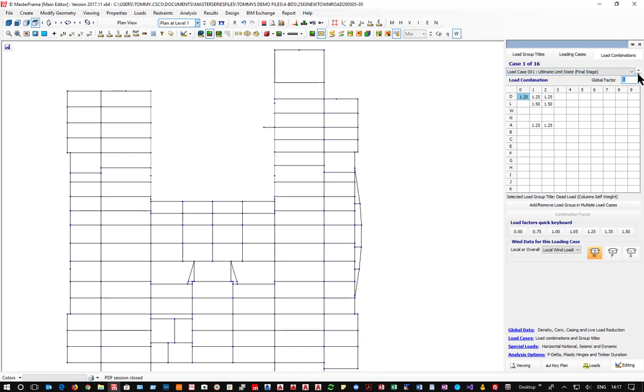If you look at the next one, we've set them up twice. Those are defaults for self weights, so everything's been done twice. Now we're looking at dead plus live, but in fact it's only done it for one set. So in reality, he is not going to get his patterns.